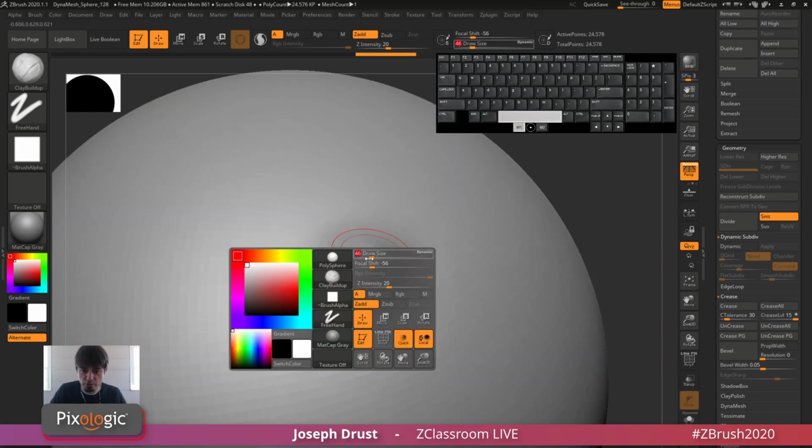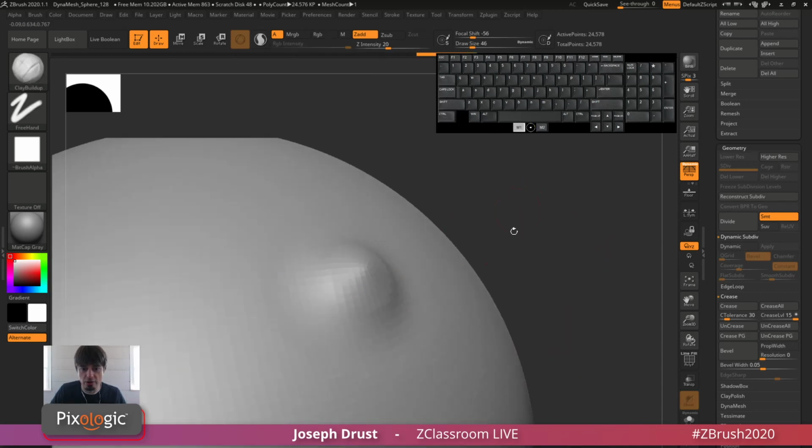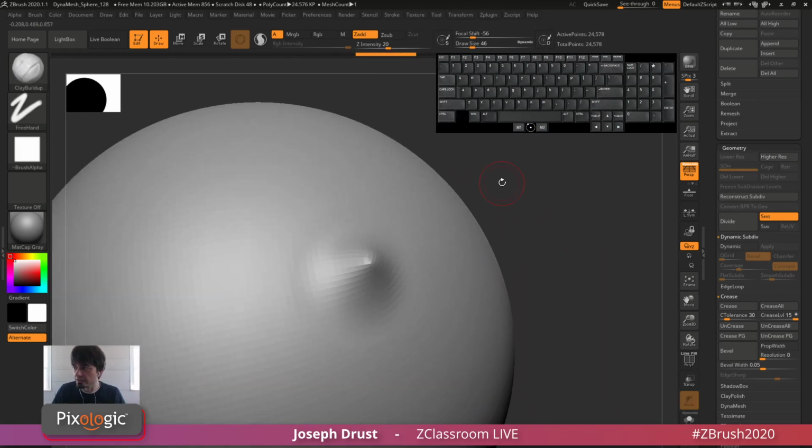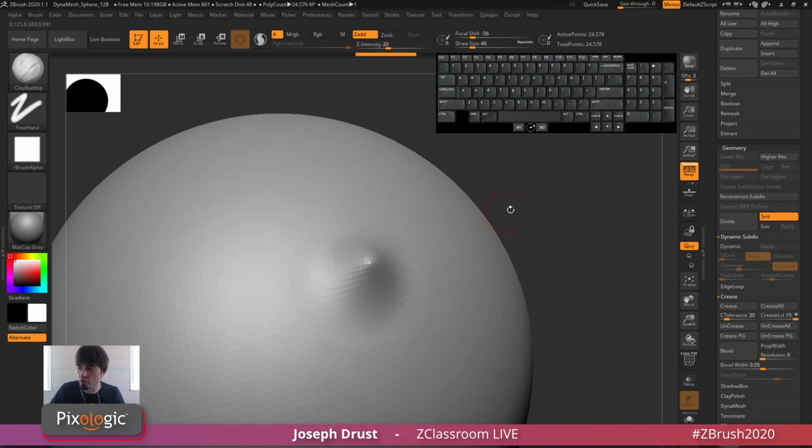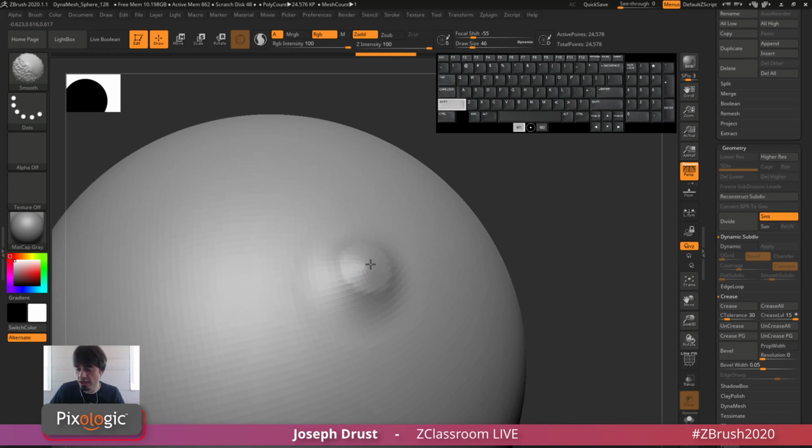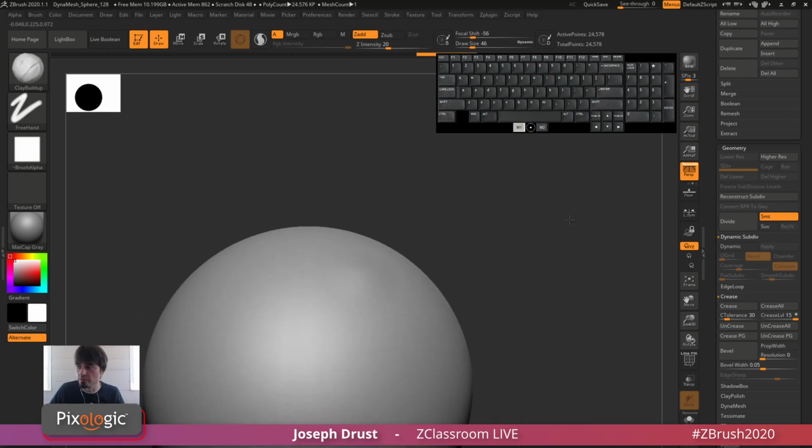So when you start smoothing this, you're going to see the difference in this zone compared to the other areas on your smooth. Now there's an alternate smoothing functionality you can do inside of ZBrush, and this will apply like a relax instead of a smooth, and it's going to help resolve any of those areas where you may have points. So for this one here, if I smooth it out, eventually I'd probably get that point vanishing, but if I want to smooth it out quickly, you can hold down Shift and start smoothing, and then release Shift, and this is going to perform this polish or relax. And this is going to allow you to remove any of those areas of topology where you may have those spikes or points. So you can see that is pretty much polished away.